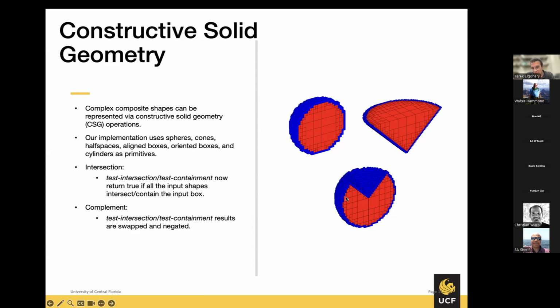If you want to capture these edges, we go further down the fidelity or resolution until we capture all these edges and represent that shape. So constructive solid geometry essentially becomes intersection, union, and containment type operations, where we use them to find what a specific sensor profile intersects with in the space that we want to cover, and it gives us what the sensor can actually look at.